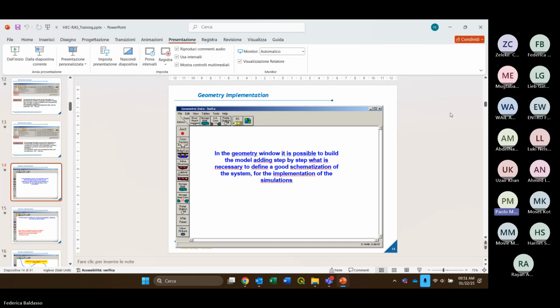In case you have a lot of money, you can do some LiDAR topography for the off-water portion, and then maybe you can survey an entire reach with bathymetric techniques, other than just cross sections. But regardless of the technique that you're using, the main scope is to have a topographic cross section or a topographic reach completely surveyed, both out of the water and under the water. So that's very, very important. That's critical.